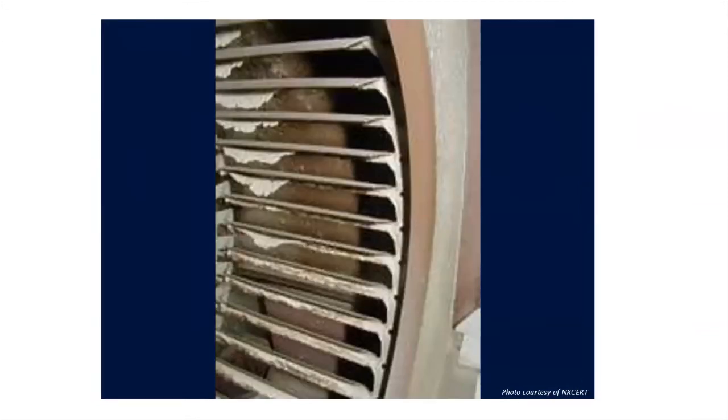Poorly placed filters, like the ones we just saw, or systems that have had the filter missing, can create this type of problem. The dust buildup on the fan indicates an ineffective filter. Clean the fan, replace the filter.